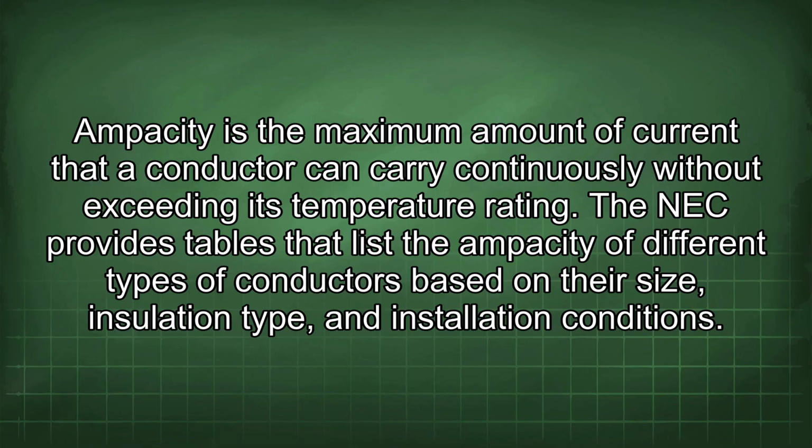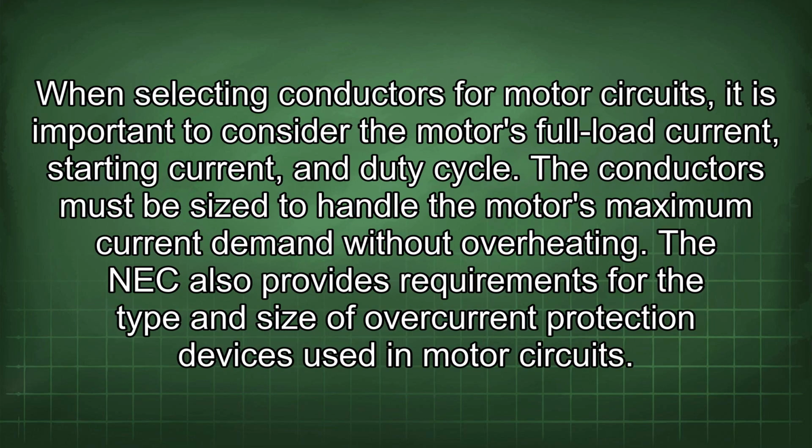When selecting conductors for motor circuits, it is important to consider the motor's full load current, starting current, and duty cycle. The conductors must be sized to handle the motor's maximum current demand without overheating.